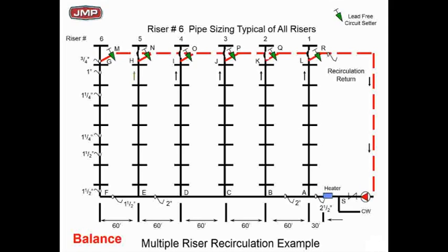That would always be wide open now. The circuit setter there would always be wide open, until I felt some warmth with my hands, just that simple. Until we got hot water there at night. With everything off, I had hot water flowing through that piece of pipe. And then we gradually changed the setting on all of them so every riser at night had hot water touched